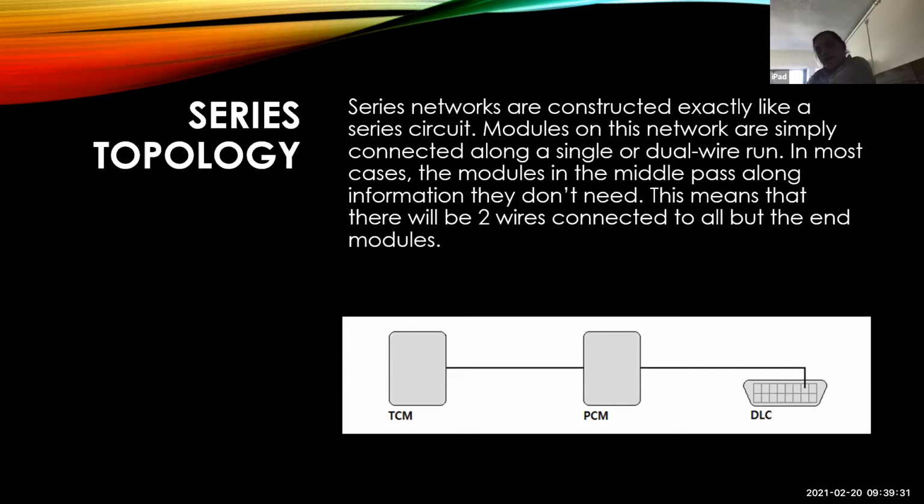Or how about output from the PCM? Could be. So I need to double check that too. So you just check continuity on the wire and then see if you get something? Yeah, I usually use a lab scope, and what we'll actually do, and I've got this coming up, I'll use two channels of the lab scope, one at the TCM, one at the PCM. Okay. Is the signal the same? It should be. It's supposed to be electrically the same.